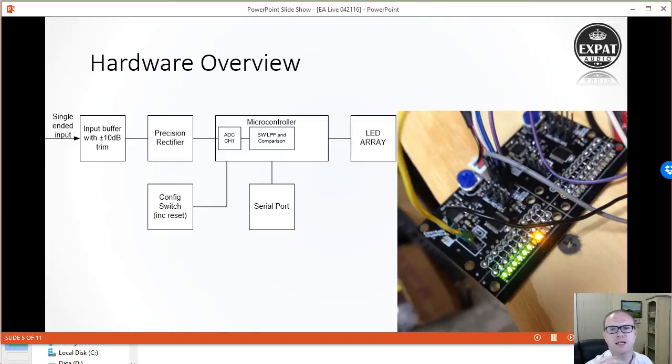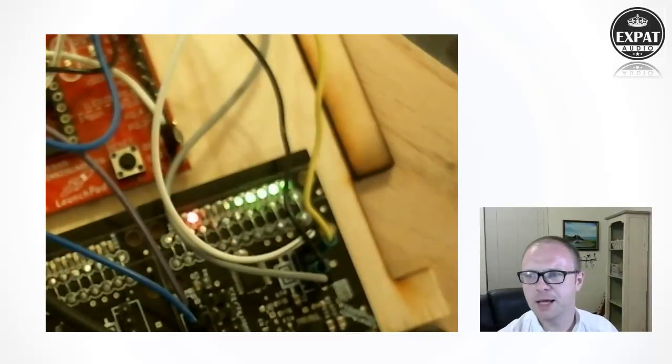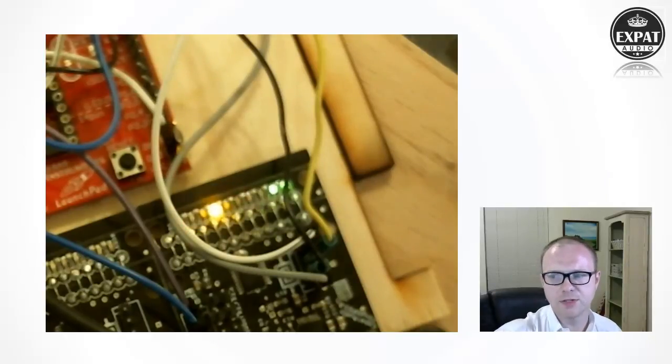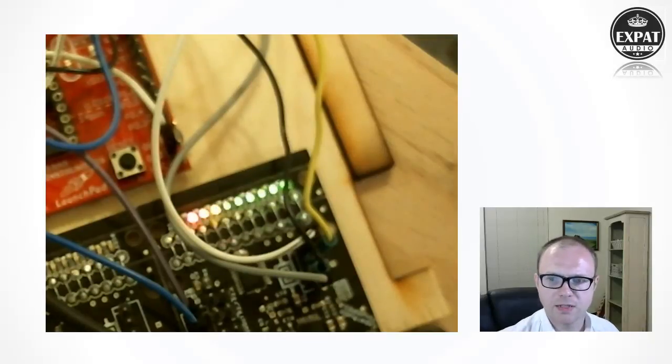So that happens in the ADC, in the software, you can see it here. We do a low pass filter in the comparison and so on. And you can see the board, you can see it working. Let me jump to here. So I've actually got a little drum loop running into this. You can't hear it right now because we probably have some kind of feedback, but you can see that it's a drum hit, and then there's a peak hold going on there, and some filtering to be accurate to the VU standard, which is the integration time, how long it takes for a lot of power to increase the level. All right, let's move on.